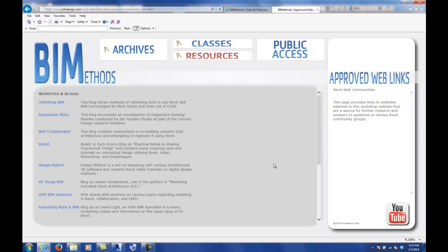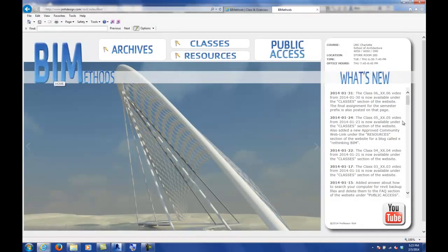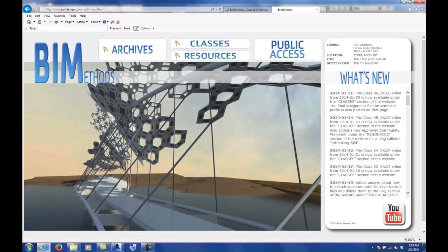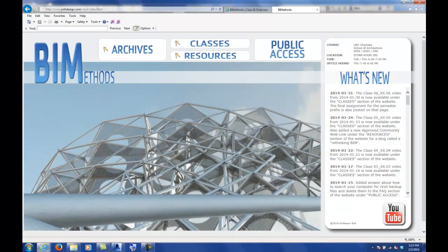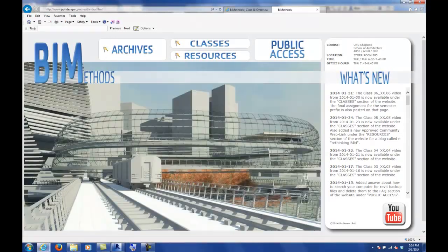But some of the things I want to echo: I think this was a great introduction to getting your feet wet, and really the best thing to do is just dive in and try, mess around with things, and learn from trial and error. I want to stress again, don't use the default assembly systems. If you think about it, those were written by software engineers, right? They probably consulted with architects to understand where those positions were, but this program is written by software engineers, not architects. So don't rely on the software to design your assembly systems. You get in huge trouble.